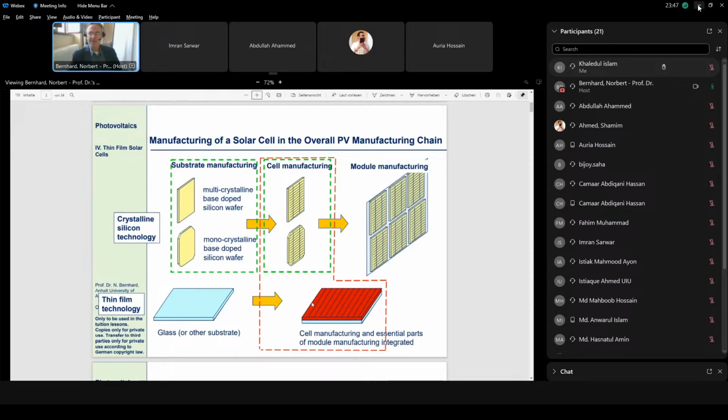Okay, let's start with the oldest of these materials and the oldest cell type in the market, which is amorphous silicon. The a, of course, stands for amorphous, and the H stands for hydrogen, because this material is always hydrogenated. If you start from the glass side, we first have the glass, then we have the TCO, which could be tin oxide or indium tin oxide. Then we have the p-doped layer, very thin. Then we have an undoped, also called intrinsic layer. And then we have the n-doped layer. And then we have a metal back contact, which also can be different metals.